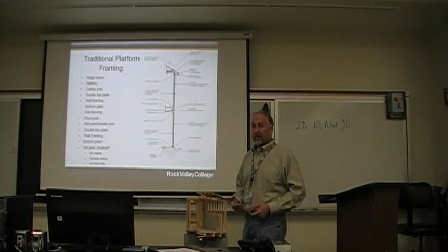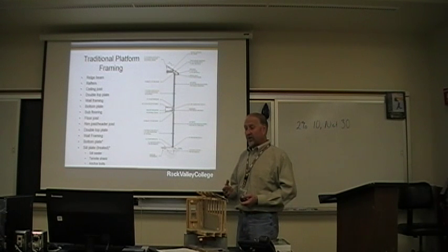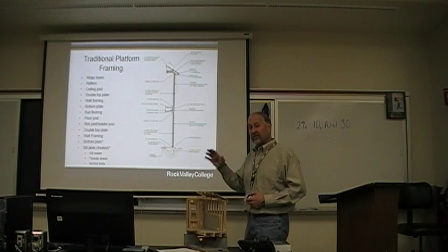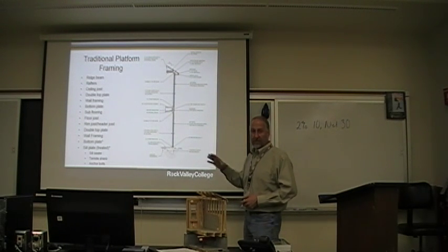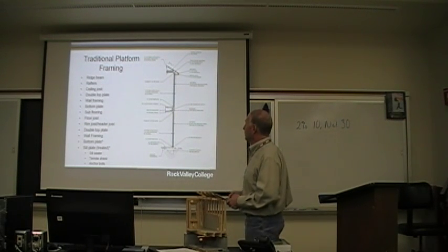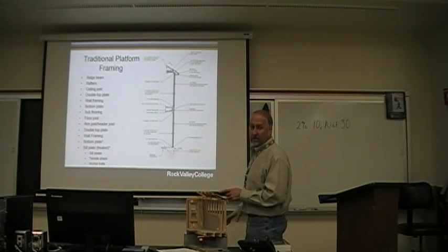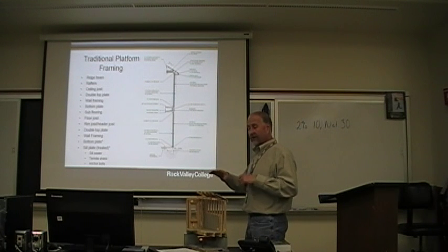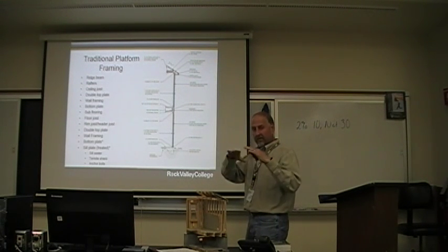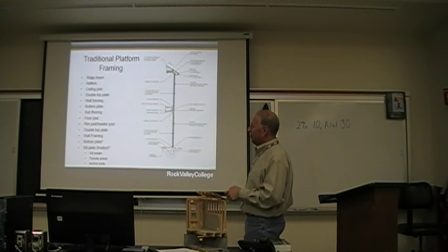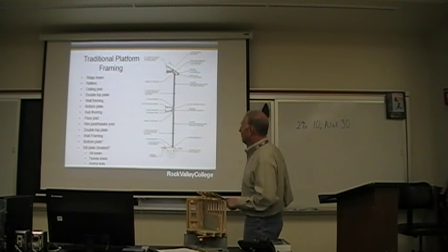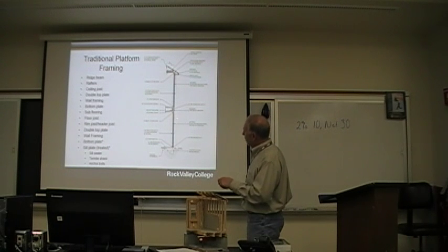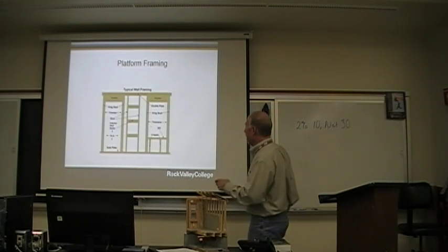They're fast, they're pre-engineered, you don't take nearly as much time, so we can get this structure under roof and protected much quicker, much faster. So some areas of the roof we still have to stick build. When we have those complicated and very involved roof sections that come in at different angles, we still need to do some of this stick building. So we have two sections. We have a wall section here, wall section here. I'm going to jump ahead, we'll come back.